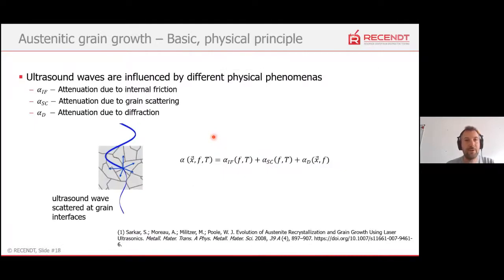At first I want to give you some basic information on the physical principle. Ultrasound waves are influenced by different physical phenomena. There's the attenuation contribution due to internal friction, which is very weakly frequency dependent. Then there's also the attenuation contribution due to grain scattering, which we are interested in. And there's also an attenuation contribution due to diffraction.